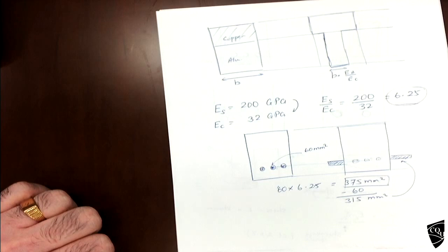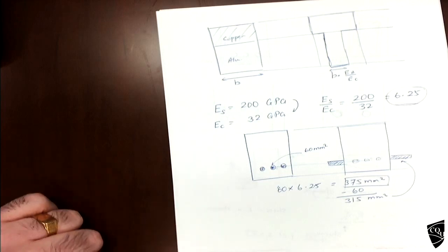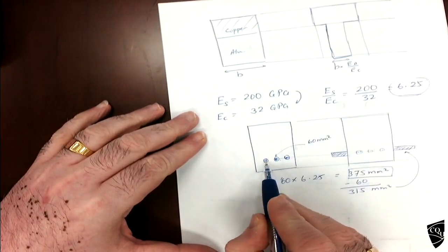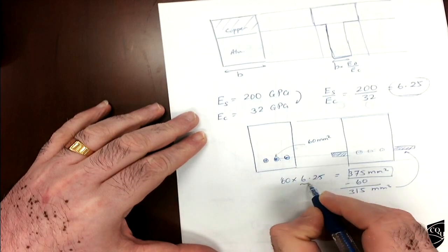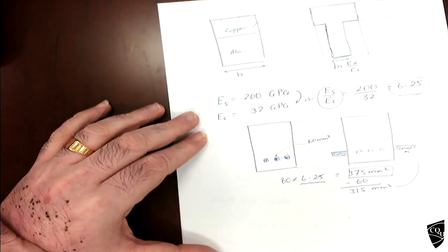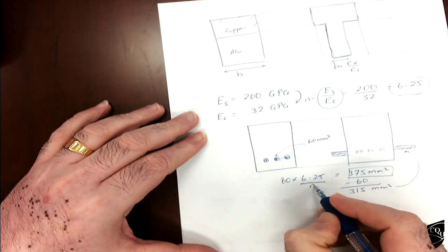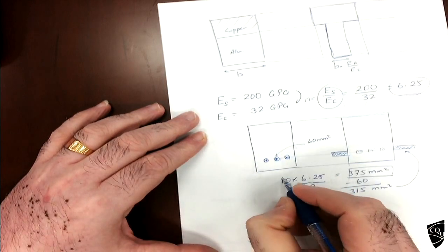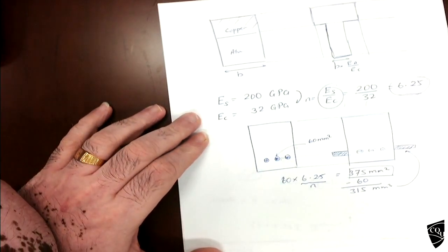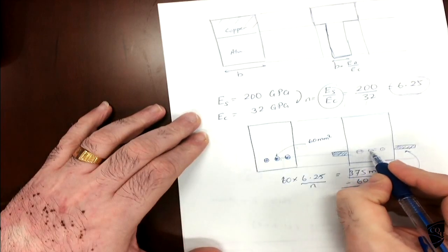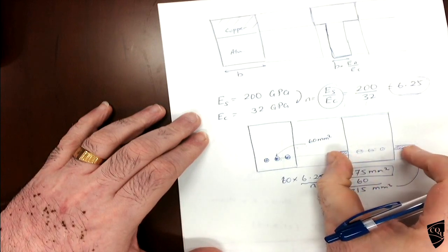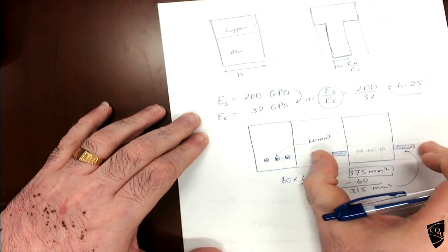A little bit tricky sometimes. So first I calculate how much equivalent concrete. This is N times the area, where N is the ratio of the E values. One part of that will fill the holes; the rest will come as an additional attachment here.